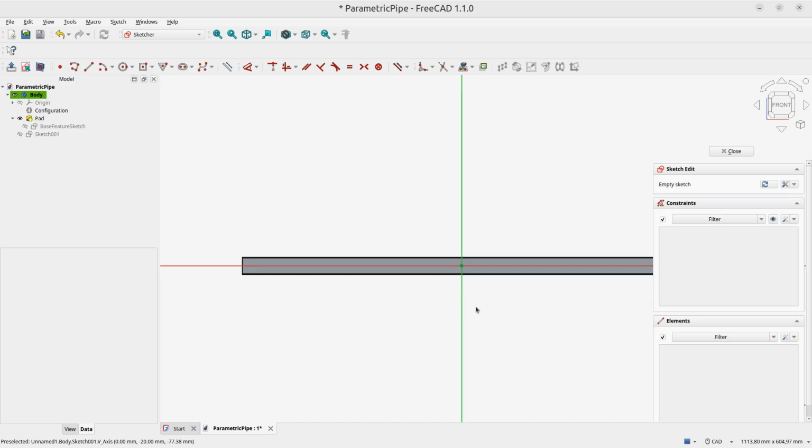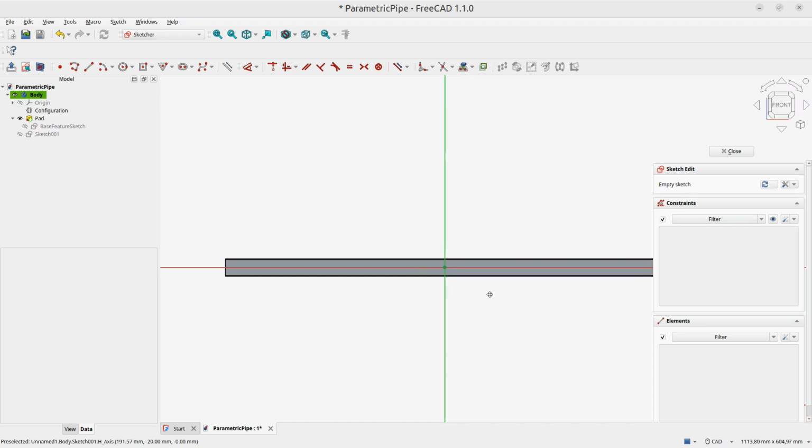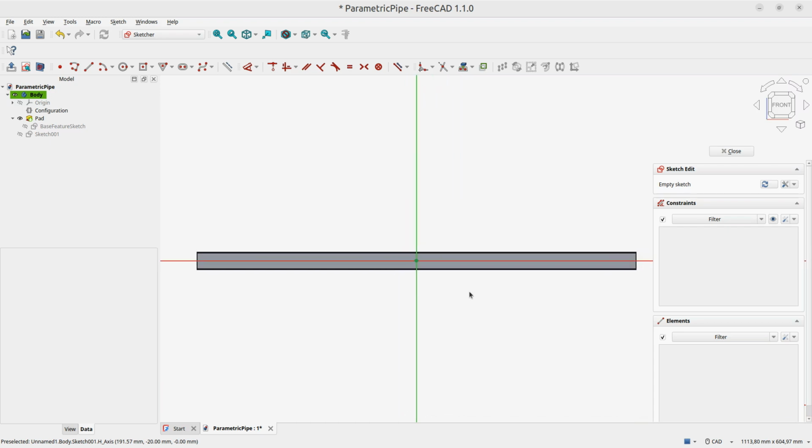This attaches the sketch to that face of the part, which is not what I usually would want to do. I would usually want to put that sketch on the XZ plane. In this particular case, however, it's more useful to have it actually aligned with the face of the part, because that means the geometry of the faces after the cut here won't be cut in the middle, which makes things simpler once you get to assembly.